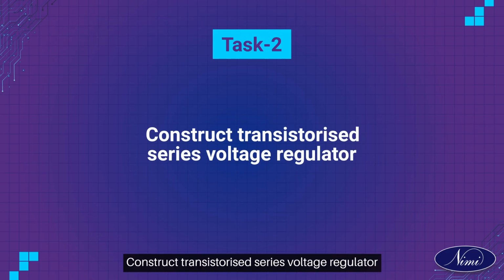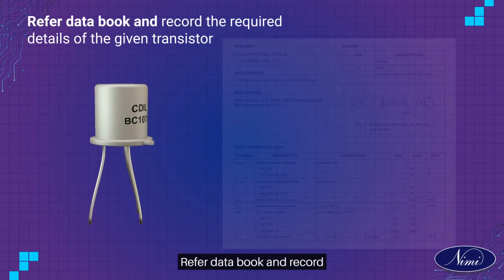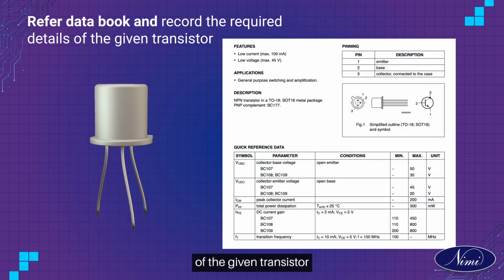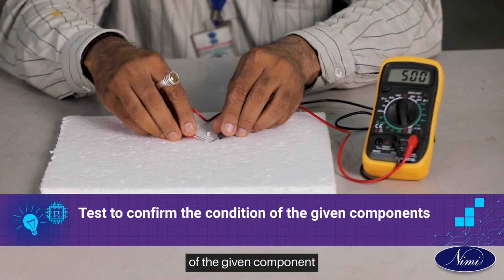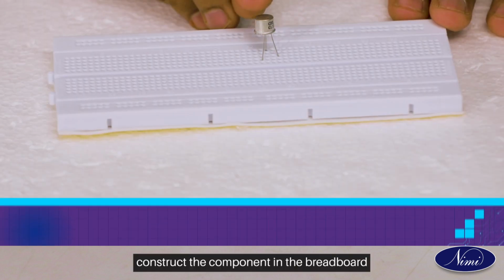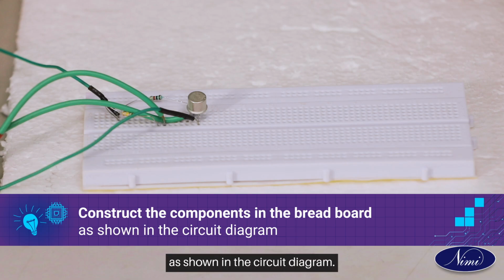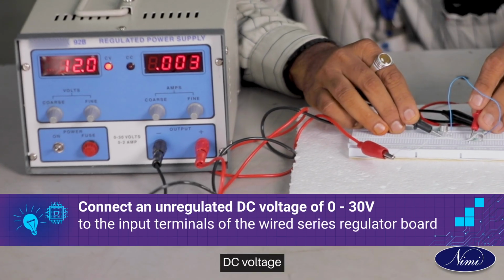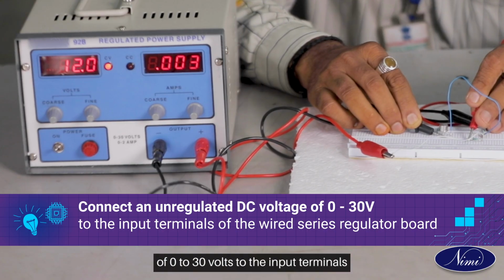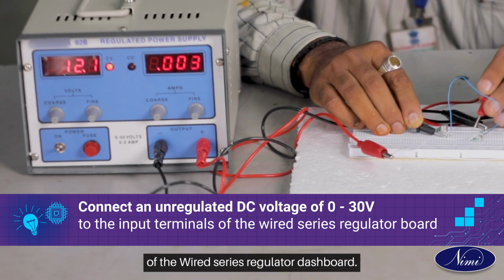Task 2. Construct transistorized series voltage regulator. Refer data book and record the required details of the given transistor. Test to confirm the condition of the given components. Construct the components on the breadboard as shown in the circuit diagram. Connect an unregulated DC voltage of 0 to 30 volts to the input terminals of the wired series regulator board.